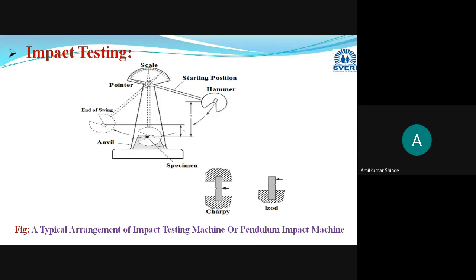triaxial state of stress. Triaxial state of stress means at a particular point or at a particular location in that material, only normal stresses will be there. No shear stress is present, or all shear stress values are zero. That condition will be termed as triaxial state of stress.